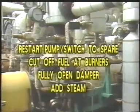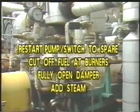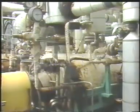Your first reaction should be to restart the pump if possible, or go to a spare. If you can't get the flow started immediately, you'll need to stop the input of heat by cutting off the fuel to the burners. The damper should be opened fully to allow the maximum amount of heat to leave the furnace. And steam should be added, which will have a cooling effect on the furnace.